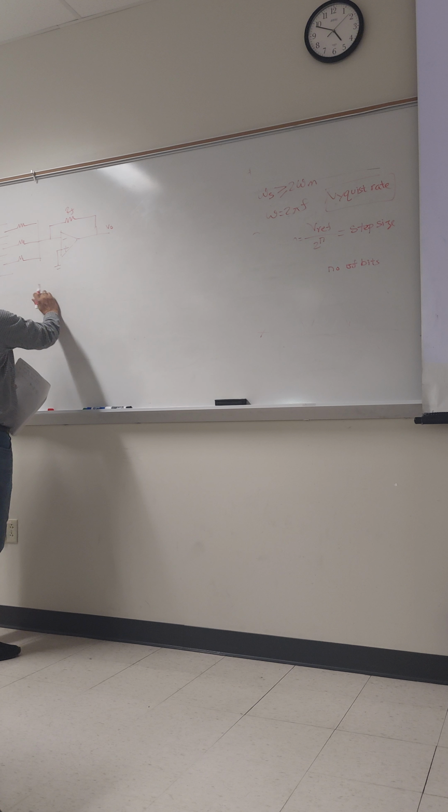And before that, we talked about the step size in detail, the step size, the resolution. Just a small recap from our previous lecture. So we saw that this resolution is equal to your reference voltage divided by 2 to the power n, where n is the number of bits.